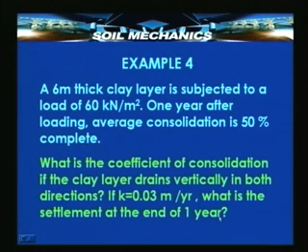The settlement that will really take place here will depend upon the final void ratio. So, we are at this point of time interested in the settlement corresponding to a particular time rather than the total settlement, and that is why we need the coefficient of consolidation here.